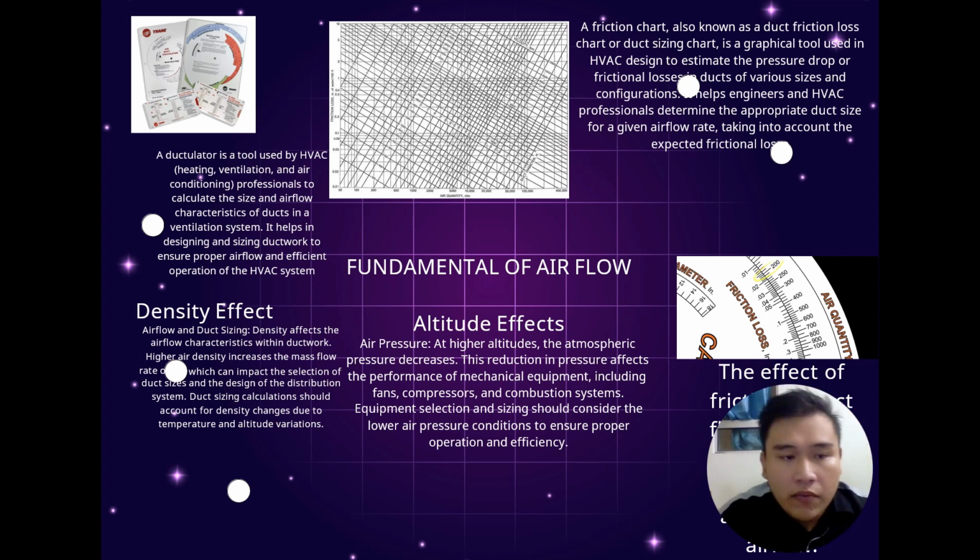Now, we will proceed to the altitude effect. At a higher altitude, the atmospheric pressure decreases. Thus, this will reduce the performance of mechanical equipment, including fans, compressors, and combustion units, and equipment selection and sizing should consider the lower air pressure to ensure proper operation and efficiency.